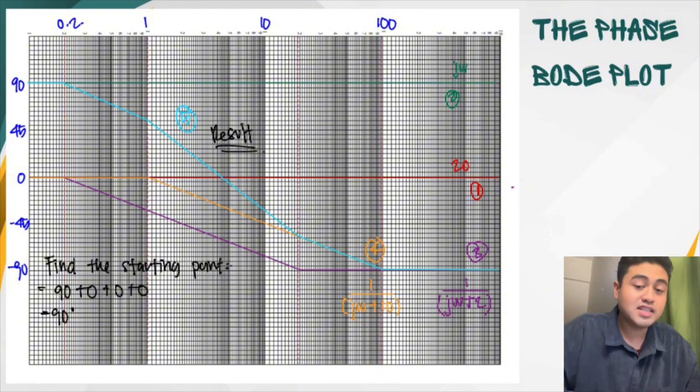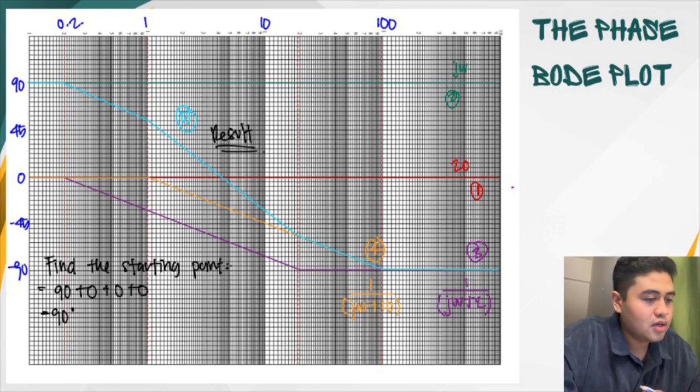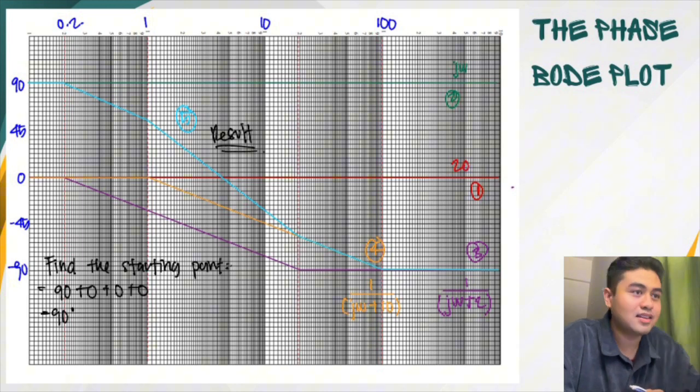So first, we need to refer to the Bode plot. The table of the Bode plot stated that the simple pole graph will start at 0, and then it will slope down when it reaches p over 10. For graph 3, p over 10 is 0.2. I think the purple line is the third graph.